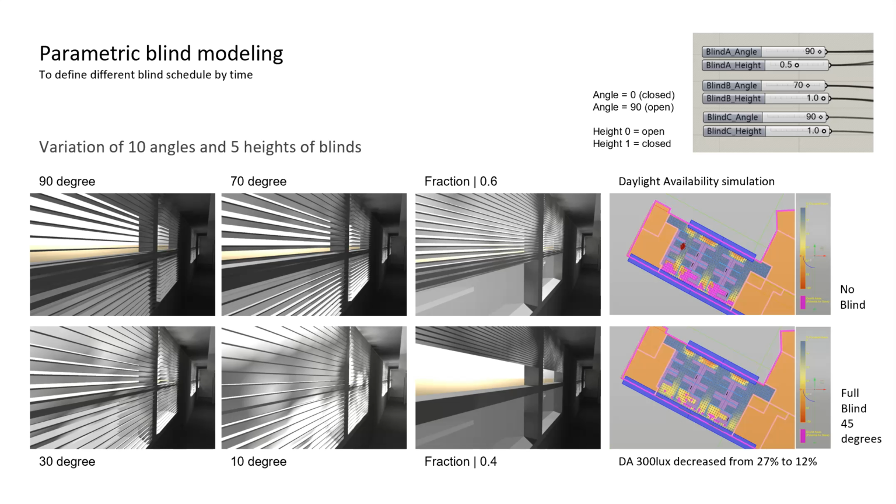As you can see in the photos on the right, top and bottom, the pink area is the overlit area. Overlit means there's a huge possibility of more glare problems for human eyes. In that section we have three different workstations that are occupied all day, so we need to reduce the amount of glare on that specific work plane.